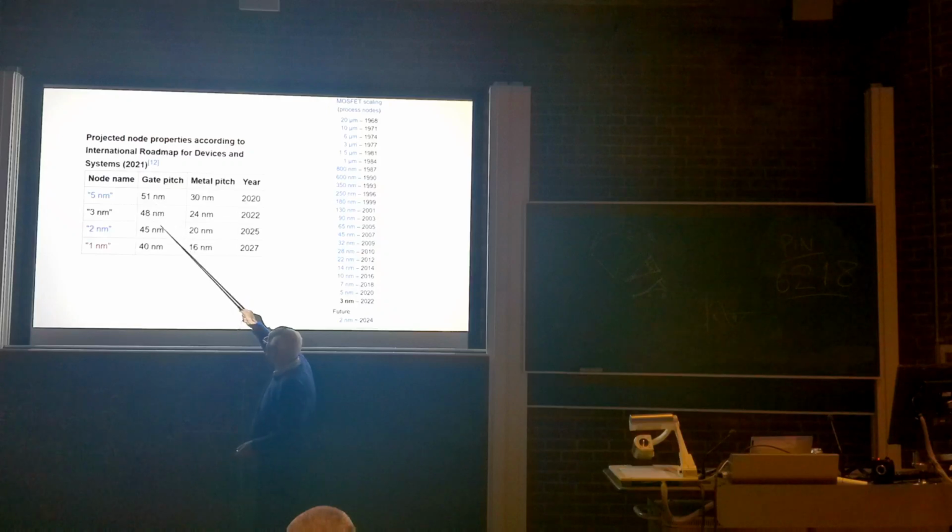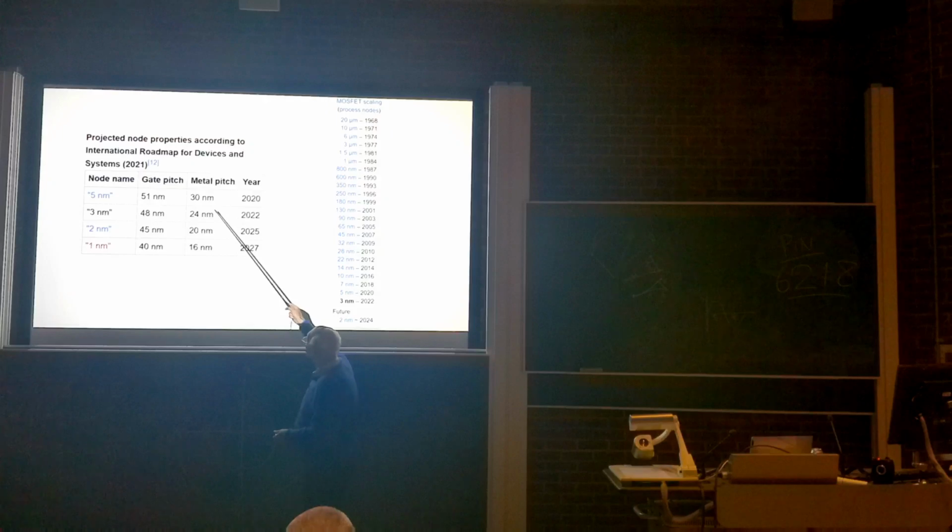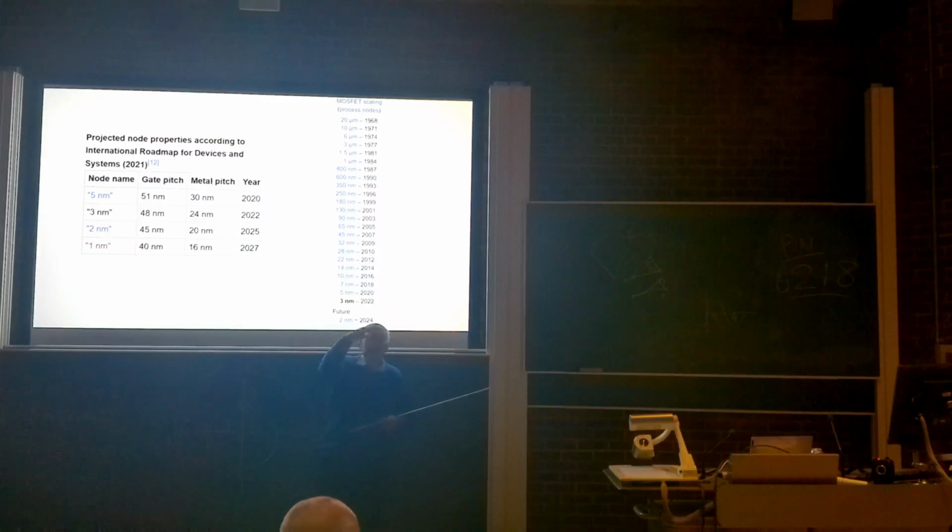So in fact, the gate pitch has actually barely changed. The metal pitch, that means the interconnections which go into it, have improved, but only by a factor of 2 over 7 years. But then you've got stacking as well to take into account, and if you take into account performance as well, you can argue that to make that curve continue on.